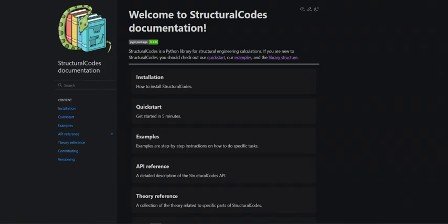I think the most challenging part was to stitch all the section API together. Yeah, I bet. From the very beginning, we knew that we wanted a modular approach, being able to swap objects in and out, and we knew that we wanted a really flexible calculation tool that allowed us to model an arbitrary geometry with arbitrary reinforcement layout.